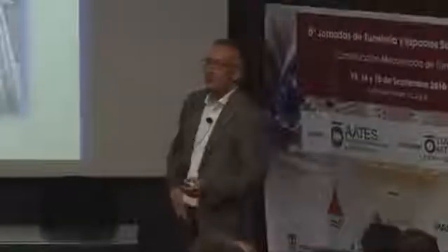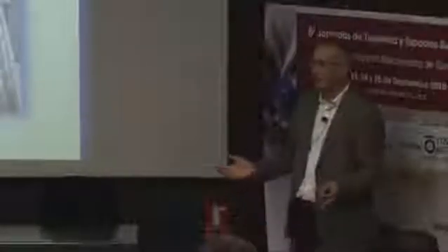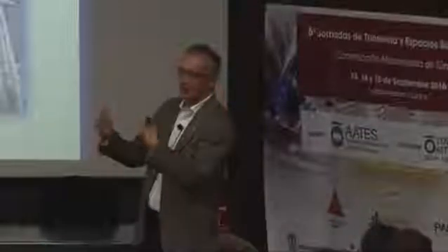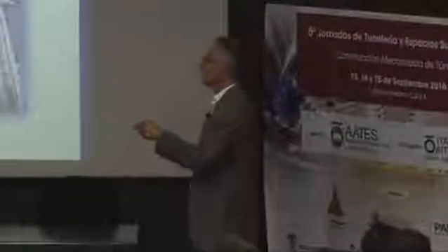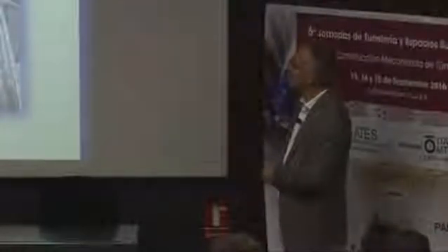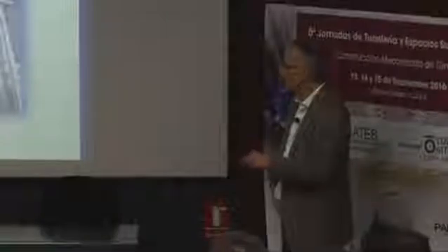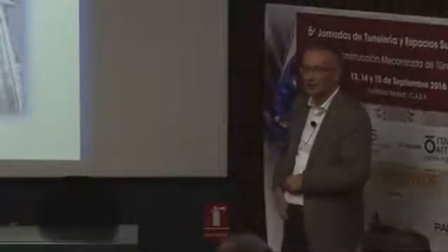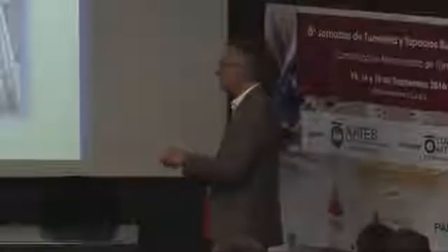What happens if you don't? As I mentioned before, at every TBM operation, you normally have some critical moments where you are about to lose the tunnel face, the active tunnel face support. You can have face collapses here. You can have, if it's a little bit more extreme, sinkholes. You can have blowouts. This is right in the middle of a field with a bentonite suspension coming out, blowing out. And you can have as well, due to your uncontrolled operation, excessive wear in your cutter head.